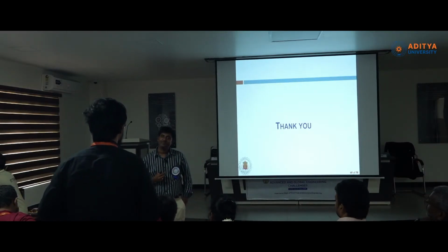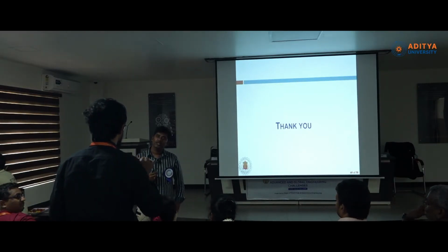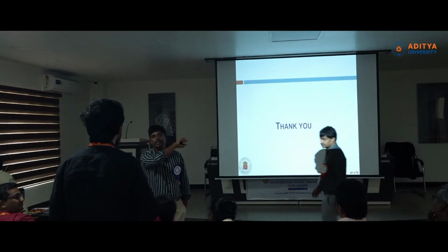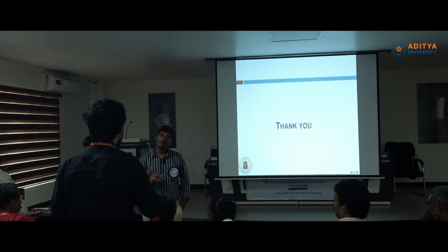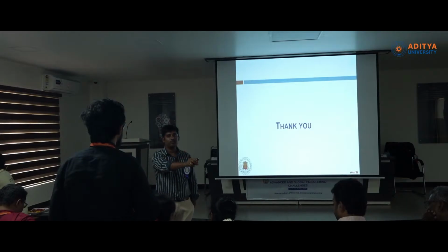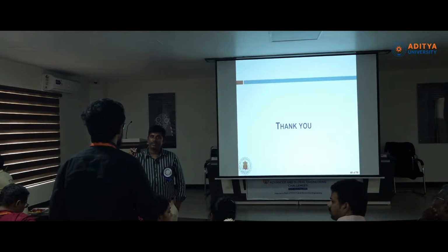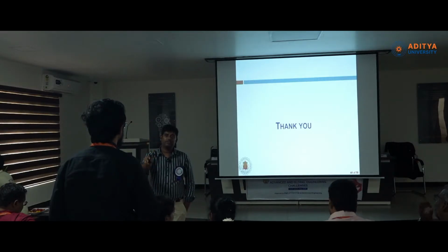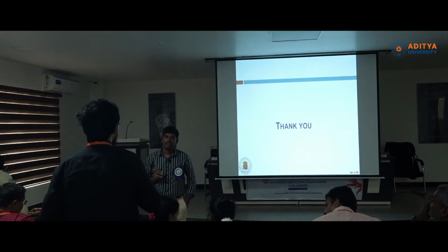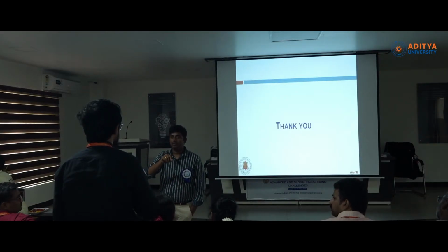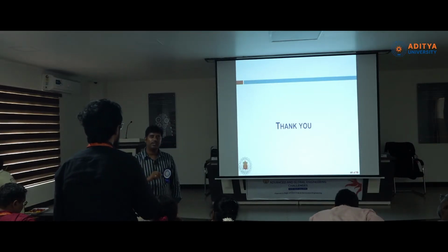Like in pollution control, if you are using it for exhaust treatment, the exhaust is sent directly into the reactor. Many gases will be there. The majority is NOx, nitrogen oxides. Along with that CO is there, and a portion of SO2 is also there. But in diesel exhaust, the majority of the gas is nitrogen oxides. CO is less. In petrol exhaust, carbon monoxide is more. But in diesel exhaust, nitrogen oxides are more.